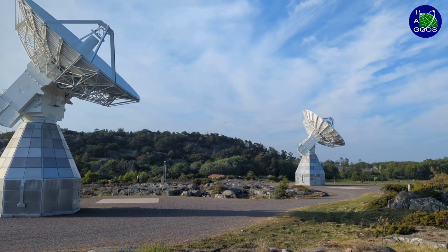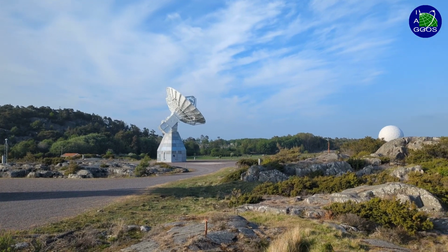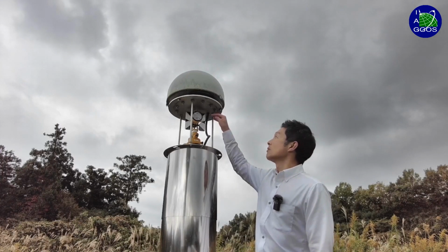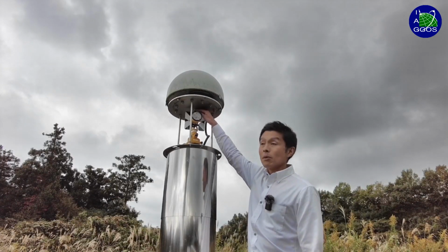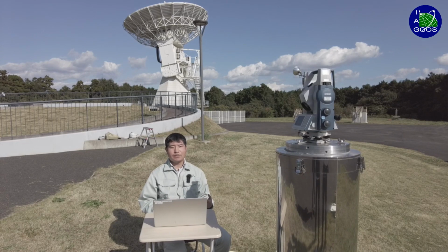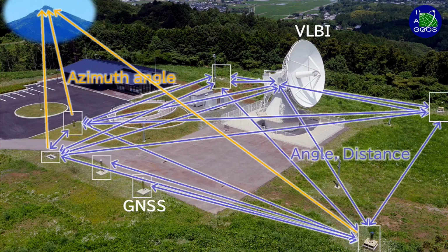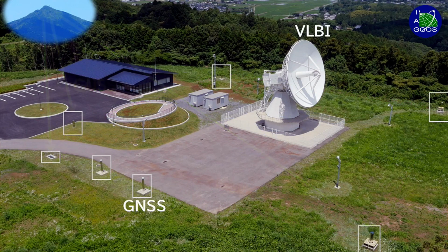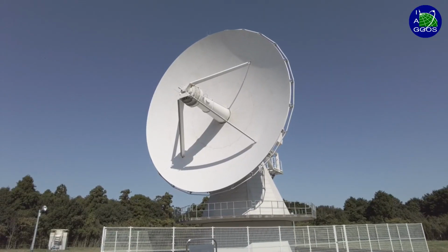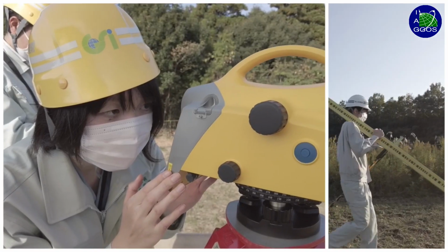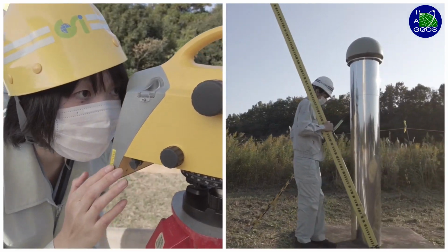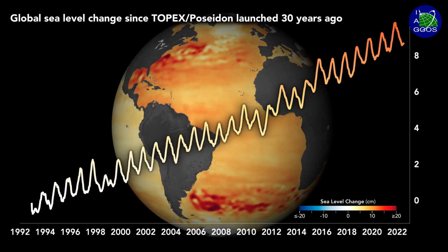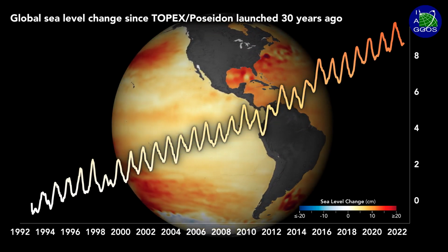Integrating the 4 technique networks together in the ITRF requires the availability of sites where 2 or more independent geodetic instruments from 2 or more techniques are operated and geodetically connected. Such co-location sites are fundamental for the realization of the ITRF. Furthermore, merging these different techniques allows the evaluation and validation of the observation quality and accuracy, as well as enabling the generation of other geodetic products.